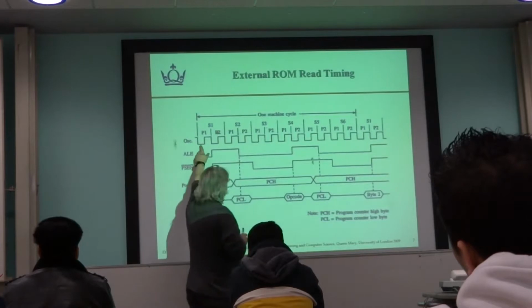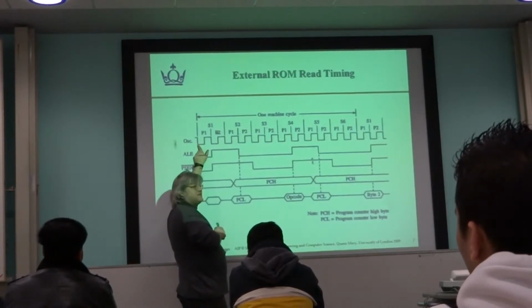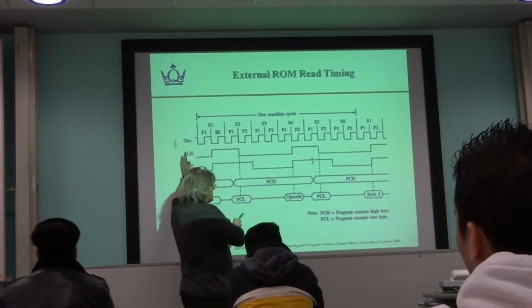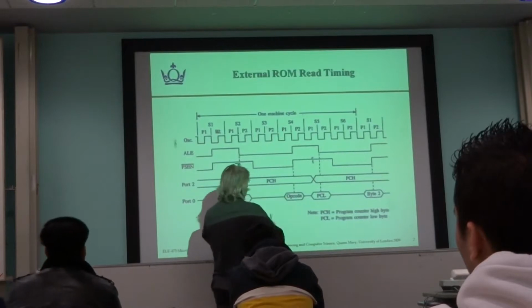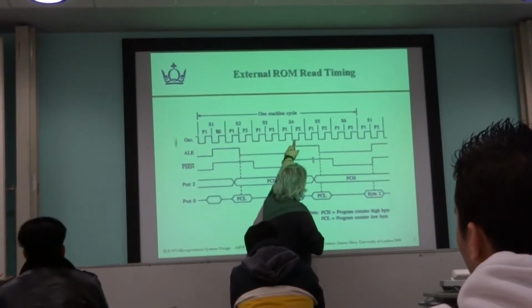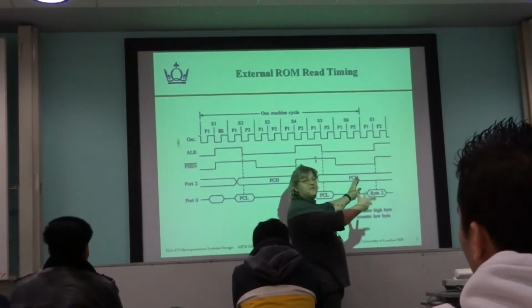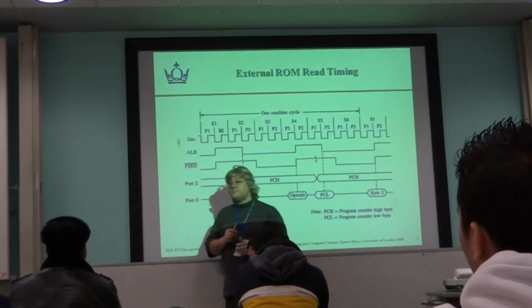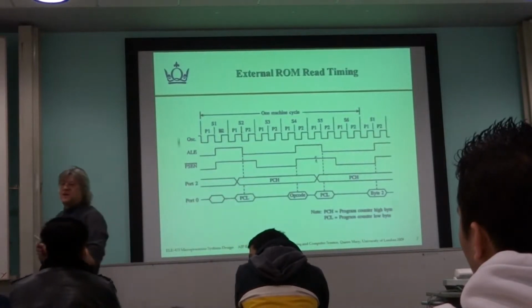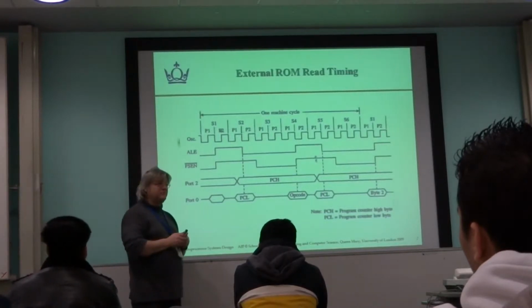So you can see it takes 12 clock cycles to complete what we call one machine cycle. Now, in this case, if the instruction was something like INC A, where there was no operand, then when we fetched it in, if you like, step 4, in steps 5 and 6 we could execute that, doing something with the accumulator, and everything will be finished by the end of step 6. So some instructions, to completely execute that instruction, will take one machine cycle.